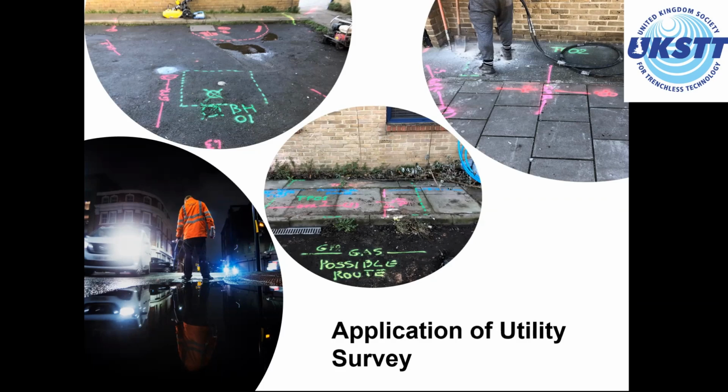Horizontal directional drill launch and receive pits, again plant avoidance whilst excavating both pits. Provision of a full utility survey, so topographical background, full survey across the site, could assist in drill profiles to determine lines of shot to see how deep they need to go. We can also incorporate GPR to find out where the bedrock is to assist with the design.